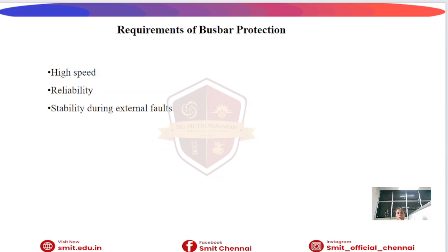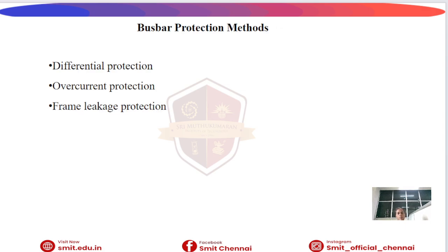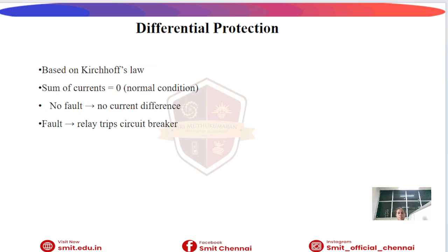Requirement of bus bar protection: high speed, reliability, and stability during external faults. Then bus bar protection methods. These are the protection techniques to protect the bus bars: differential protection, overcurrent protection, and frame leakage protection.